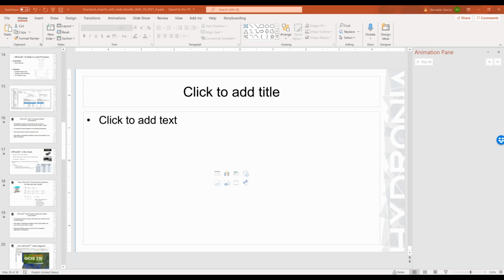However, as it is now, the model cannot account for the simultaneous occurrence of a rainfall of water or a water flow and its interaction with the oil flow. As I indicated before, the way that you can use it is you model separately the oil flow, and then when you see that the oil gets into the water, you let it go, but it will not interact. You create a cross section so that you can extract the flow hydrograph from the overland oil flow model, and then you input that into the other model that we haven't discussed today, the oil on water model. That is a separate one. So that's how we can do it now.